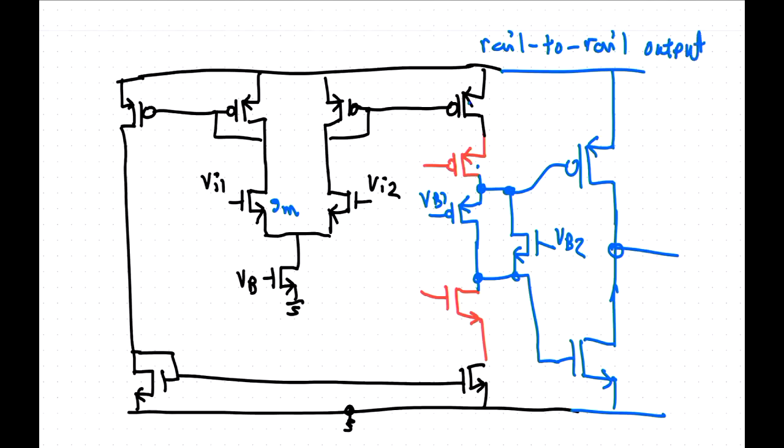Now it is a common source stage, so now you have 2 amplifier stages, so you've got to put in Miller compensation. Often you put it into this point here, or you could put it really anywhere in the stack here. It's not so important. If you put it into that, you might get a free lead compensation from the gm for that one there. But yeah, it becomes more complicated. It can be unstable because now it's a 2-stage amplifier. Even if the gain of the second stage is not necessarily high, you don't put in the second stage to get gain, you just do it to get the drive capability sitting up there.